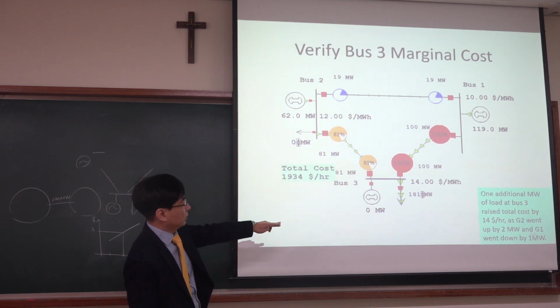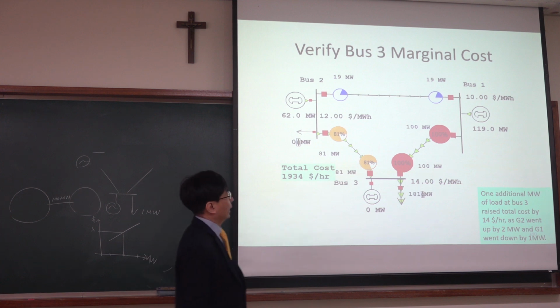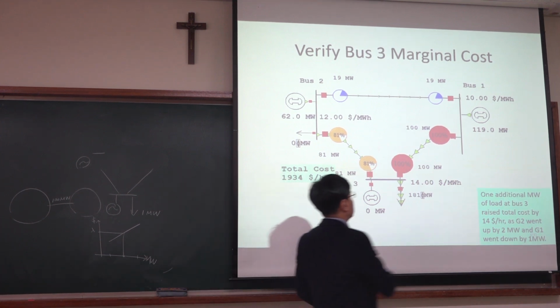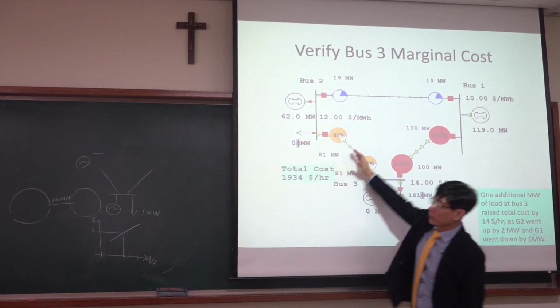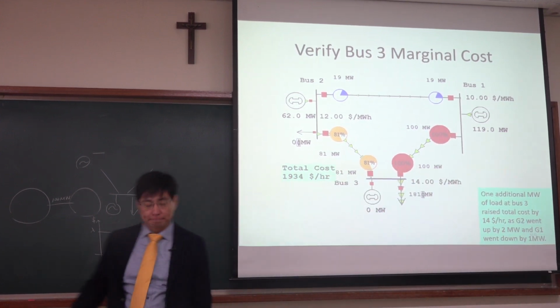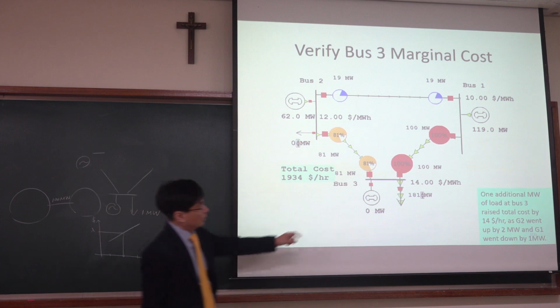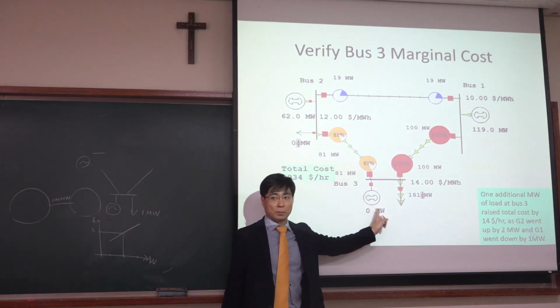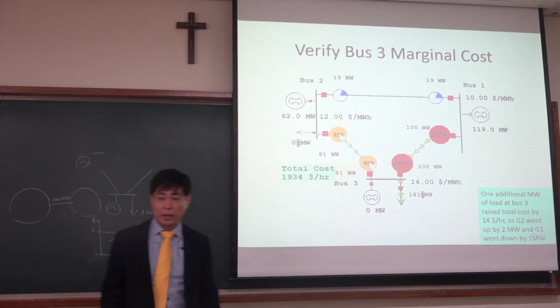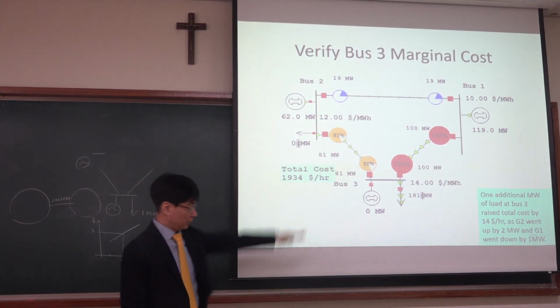Yeah, so this is the result. Okay, and the power flow slightly changes. Still, we satisfy the transmission line limits. This is more loaded. And still, this generator, the output is 0 megawatt because this is the most expensive one. So we have another way to satisfy the demand.